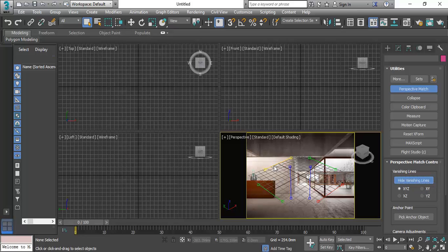So I'm going to make the X-axis my receding axis, or the one going to the vanishing point. So I'm going to move the line there so that the bottom of it is on that edge of that wall. There we go, and then drag the other end of it so that it follows the bottom edge of that wall there. I'm going to drag the Z-axis onto the same corner point, but then again have that follow, of course, the vertical axis.